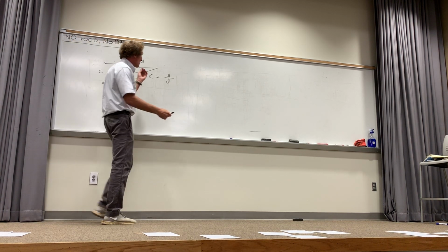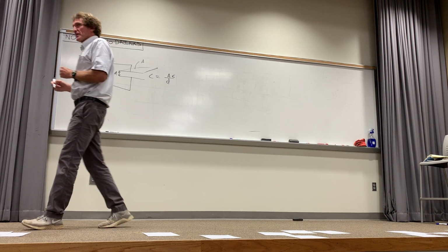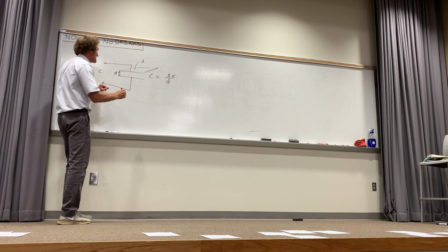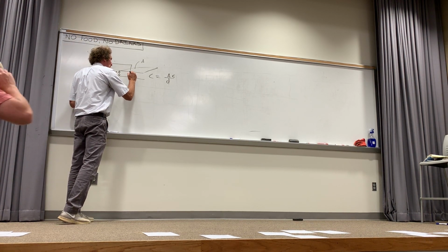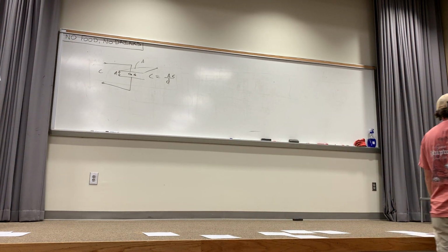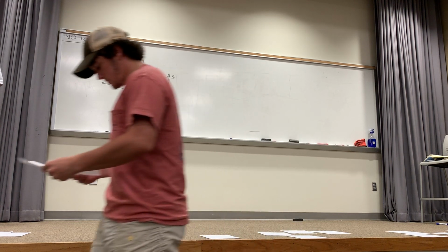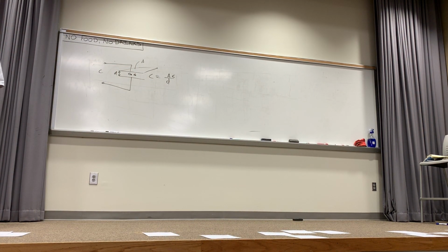The multiplier here is really epsilon. Epsilon is called the permittivity or dielectric constant of the insulator that separates these two plates. This is epsilon relative times epsilon naught, and epsilon naught is about 8.854 times 10 to the minus 12 farads per meter. Epsilon relative's value can be big. It can get up to probably 1,000 to 10,000 for exotic materials. Typical values of epsilon relative are somewhere between 2 and about 10 or 20. But these are just relative things you should keep in mind.